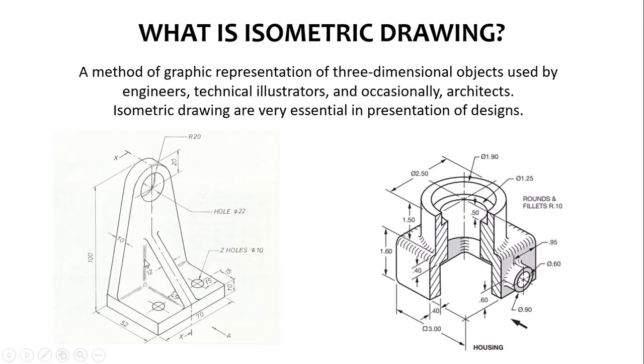For example, we could only view the top part of this drawing, or we can only view the object via the arrow A, and then we'll begin seeing certain features that are shown here but in a better way. For example, if you look in the direction of arrow A, you're not really able to see that this part here is slanting. You just see a straight line. But if you look in this direction where we've got the 52, you can see that this is a slant.